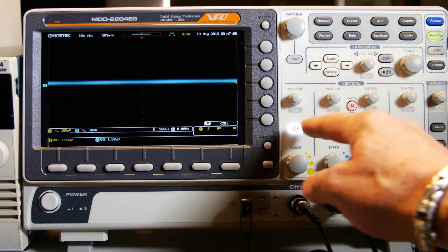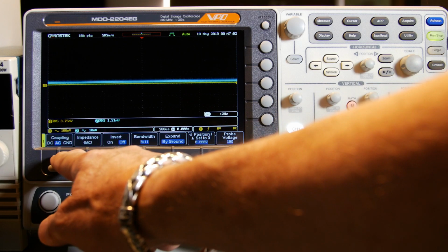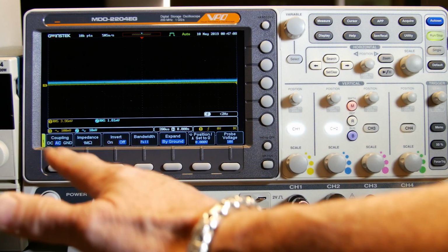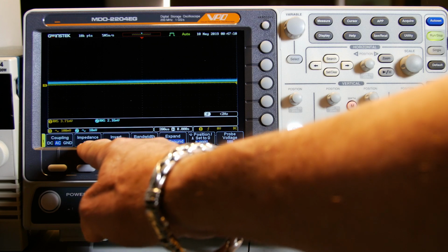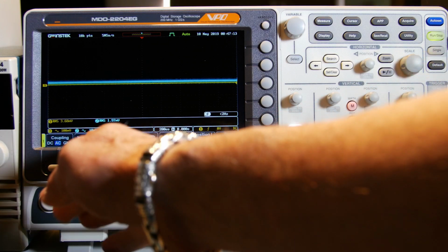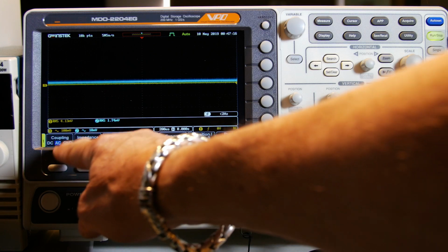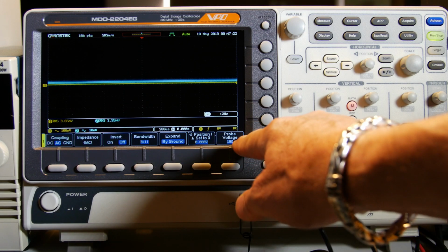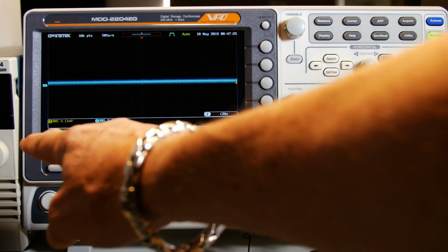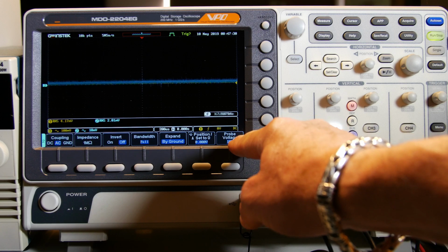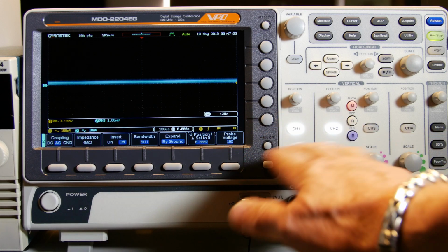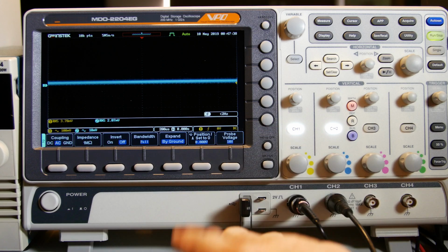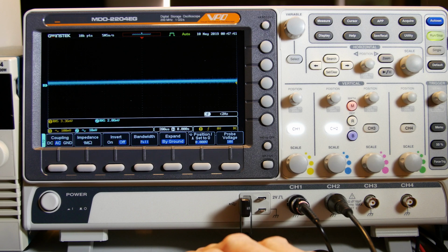Now just to show you real quick, channel 1 is AC coupling, 1 meg. I have AC coupling because we're looking at AC signals, so it just simplifies things. I don't expect there to be a DC offset, but hey, I just put it there. And then impedance 1 meg, invert off, full bandwidth, and probe setting 10x. Channel 2 is the same way. Normally I would put channel 2 on current, but it's on voltage because we're just going to do division between these 2 channels, and it's a gain setting, so it's not really going to care. So I didn't worry about that, okay?